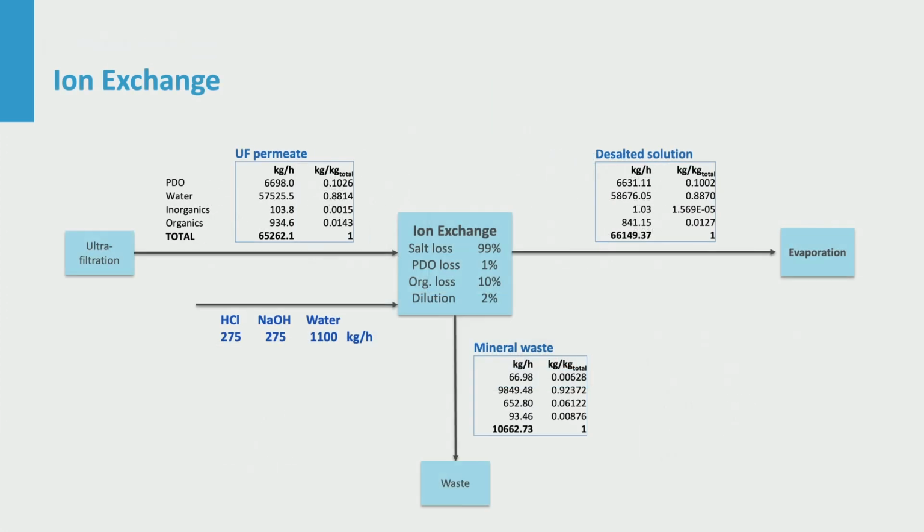Cation exchange and anion exchange will consist of a series of batch-wise steps. After sending the feed over a column with cation exchange resin in the H+ form, the column needs to be rinsed, regenerated with HCl solution, and rinsed again. Continuous processing needs at least 2 cation exchange trains that operate alternately.